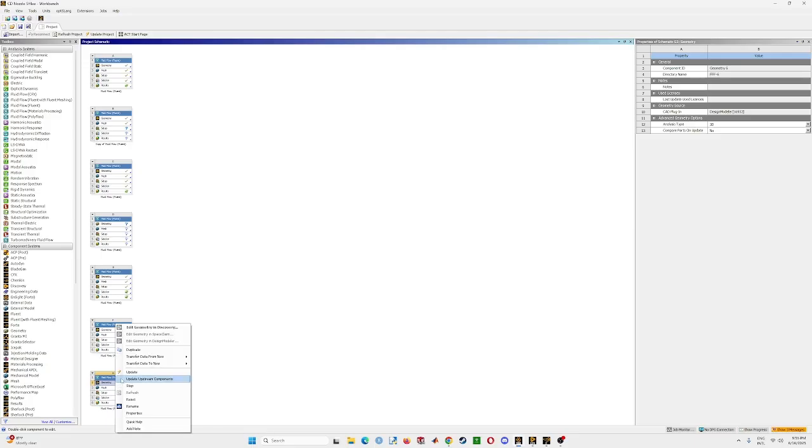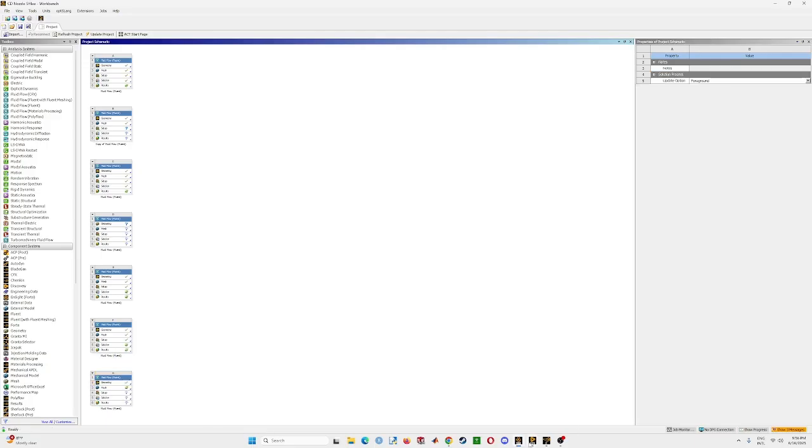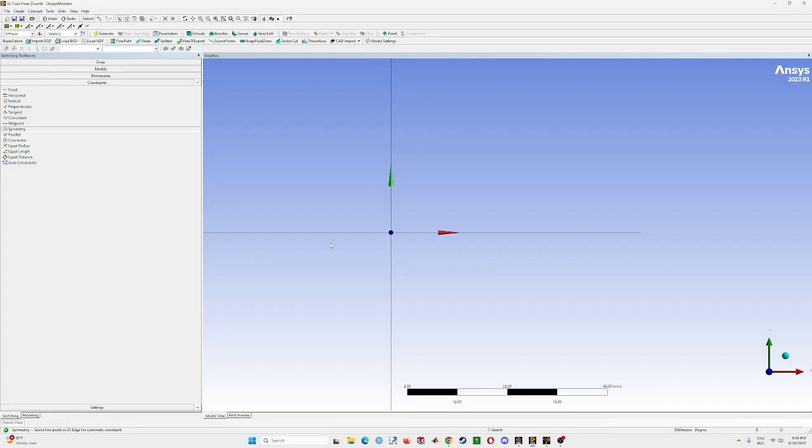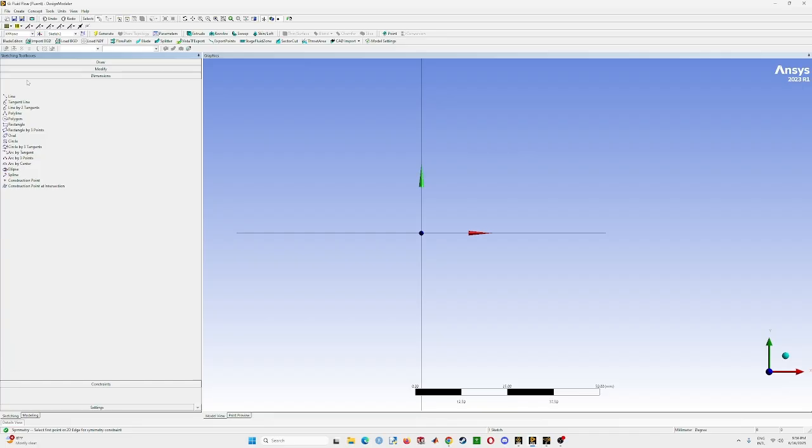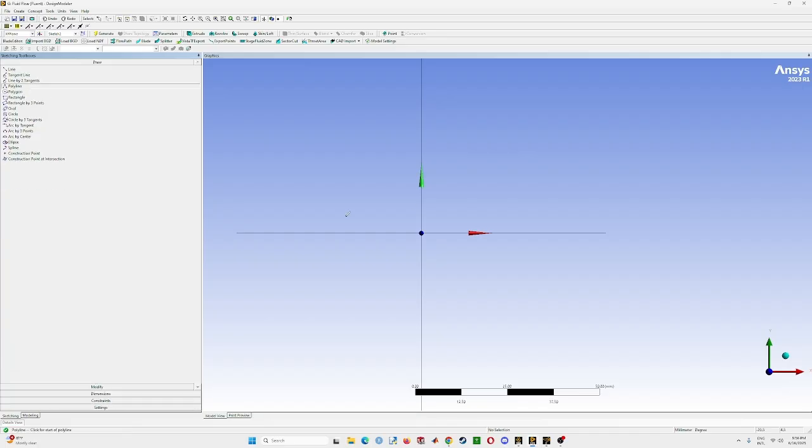So for this one here, I'm going to go into design. I already have it open here. I'm going to go to draw. I use the polyline for this from here to here, here to there, and from there and there and there and there, and then close-ended. Perfect.